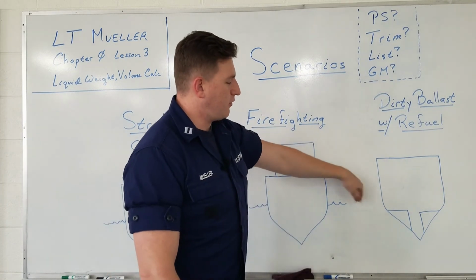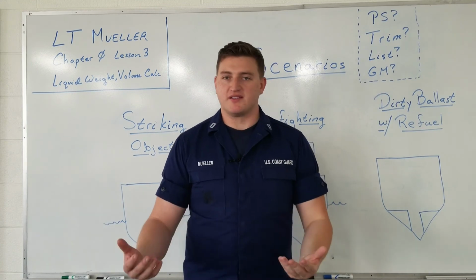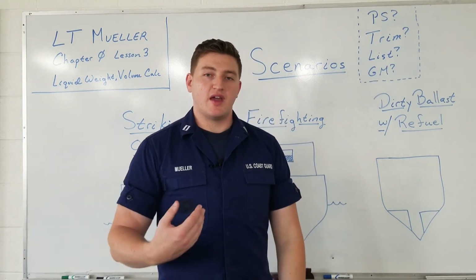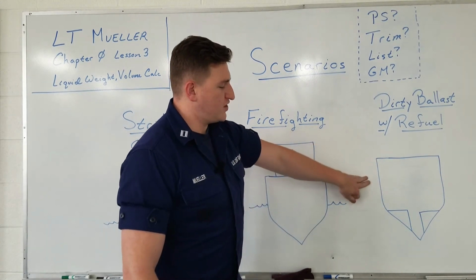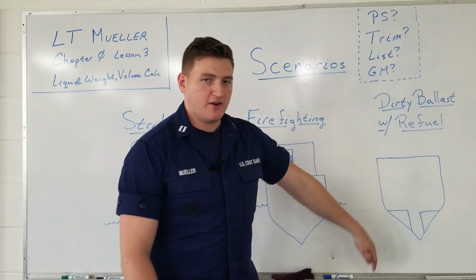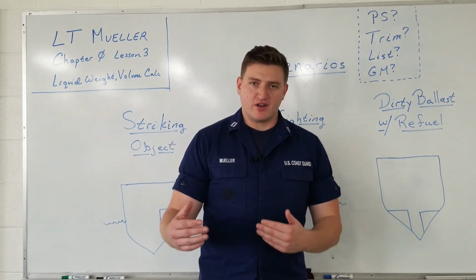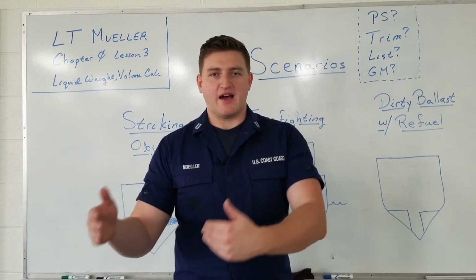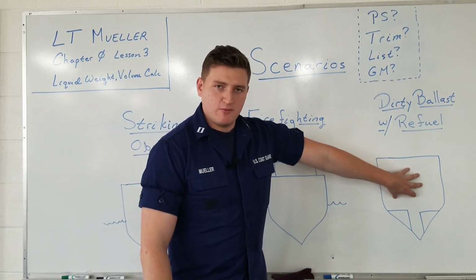Then when you pull into port, you have to have a contractor pump out all that salt water because it's contaminated with a little bit of diesel fuel. Then you have to fill those back up with diesel fuel. So now, after having one change out in the open ocean, you're going to have another change in liquid load and all the density and all the weight that's in the ship when you're at the pier. There's many different considerations when you're at the pier versus out in the ocean. How is that going to change the seaworthiness of your ship?